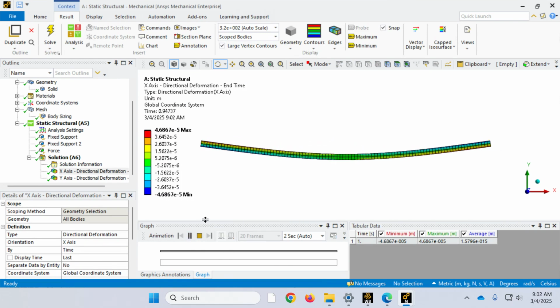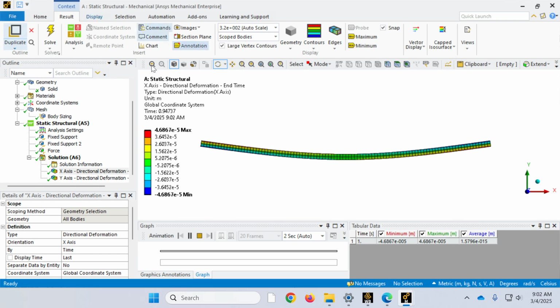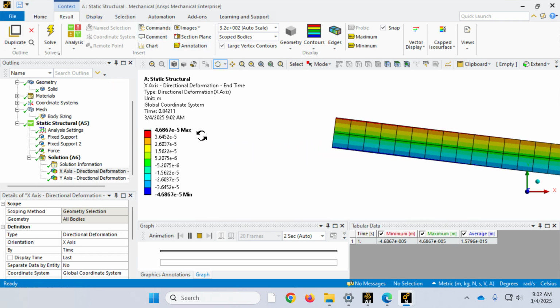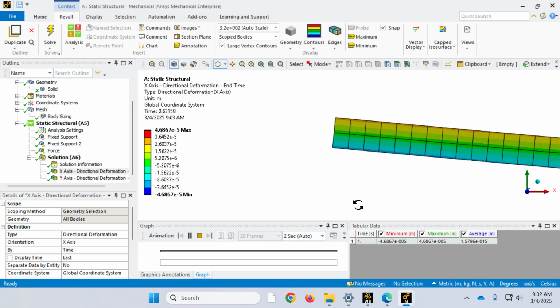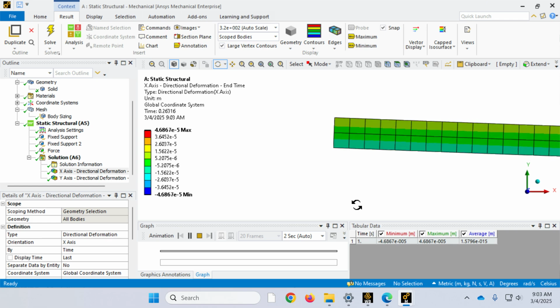If you look at the behavior of the beam, you can see that the beam is flexing in bending, and we're getting a deflection, and the front and end faces are able to rotate. So the rotation here, because I don't have a fixed support, you get this face to rotate. Hope you're all seeing that.